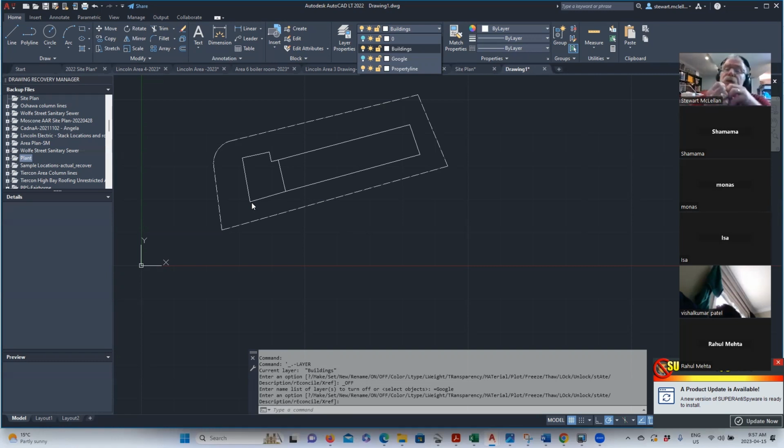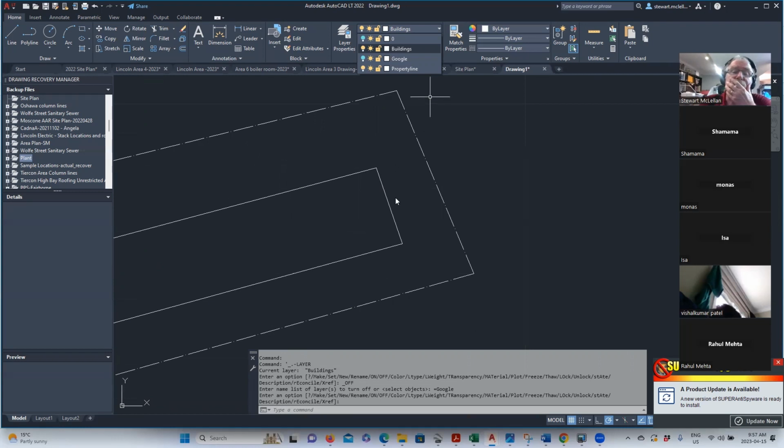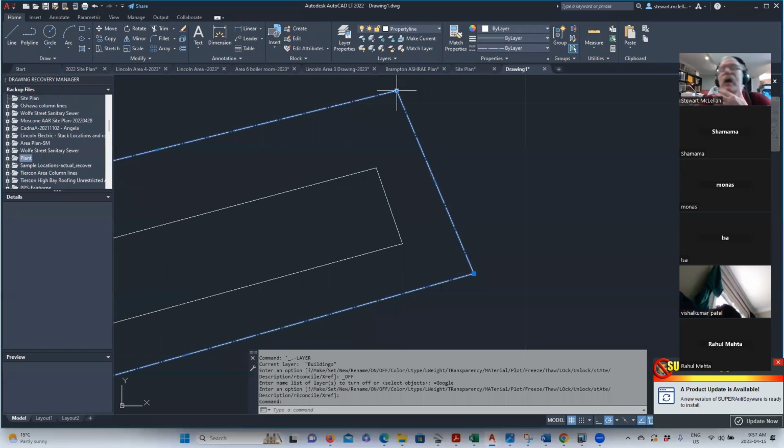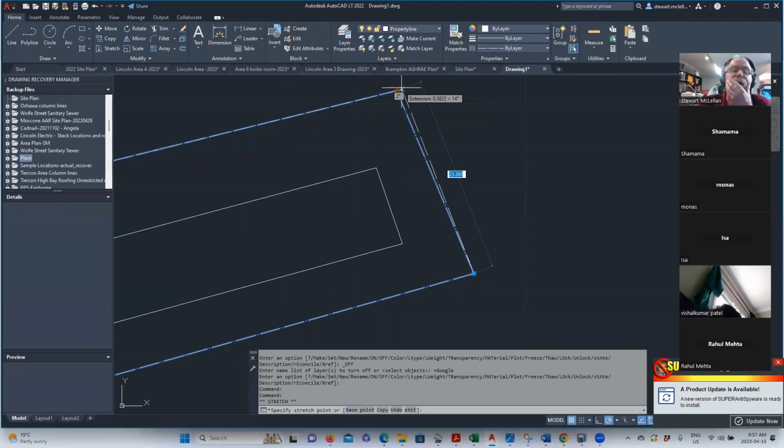We would spend some time cleaning this drawing up a little bit, right? Because you can see the building is not completely at right angles. And usually when surveyors are setting these things up, they always set things up so that everything is at a right angle.